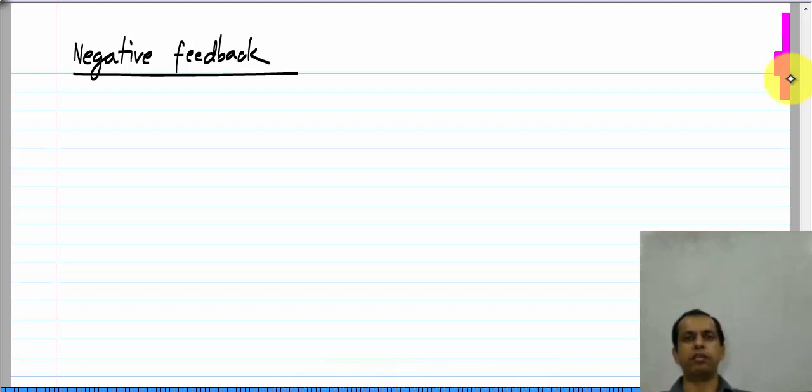Okay. So, I will give you an example of driving a car. An open loop control is when, let us say, you do not have a speedometer at all. Okay. So, if you have some strange vehicle without a speedometer, then to go at a certain speed, you have some vague idea of the speed you want to go to, and then for that, let us say you press the accelerator down to a certain extent, maybe halfway down.